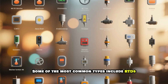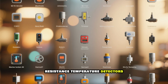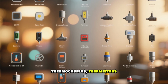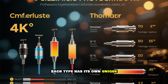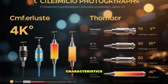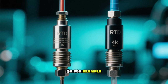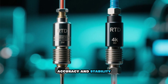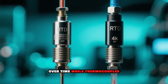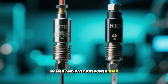Some of the most common types include RTDs, resistance temperature detectors, thermocouples, thermistors, infrared temperature sensors, etc. Each type has its own unique characteristics, accuracy, and temperature range. So, for example, RTDs are known for their accuracy and stability over time, while thermocouples offer a wide temperature range and fast response time.